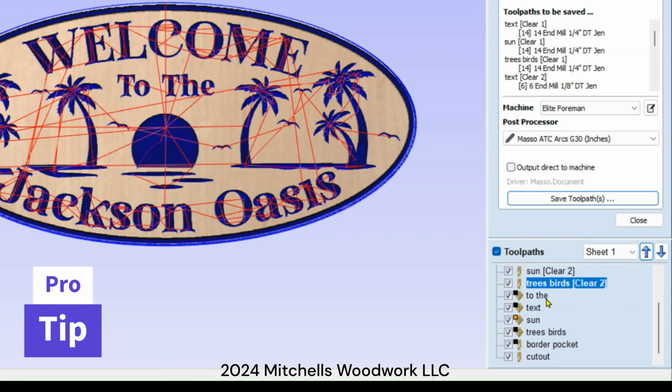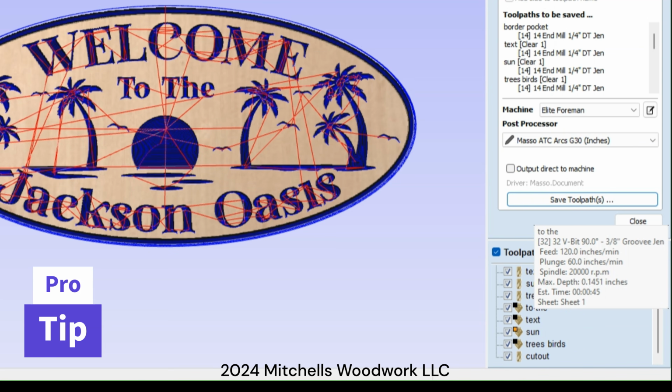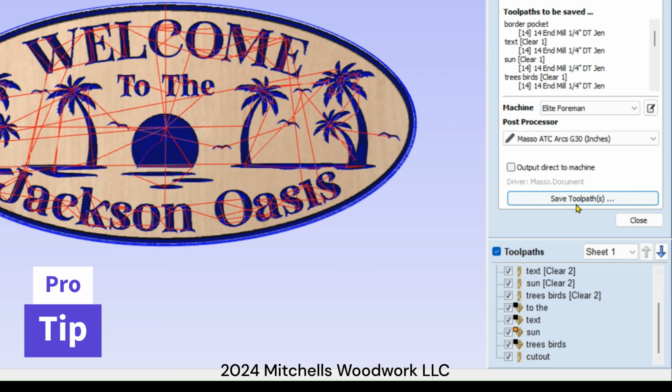All right, and then the rest of this should be, except for the border pocket. That is a 1/4 inch, so it can go up here. In fact, we can cut it first. So I moved it all the way to the top. And then the only thing left down here are V-bits, and they're all the same. They're all 90 degree. And then the final toolpath will be the cutout with that IDC Woodcraft the Beast.